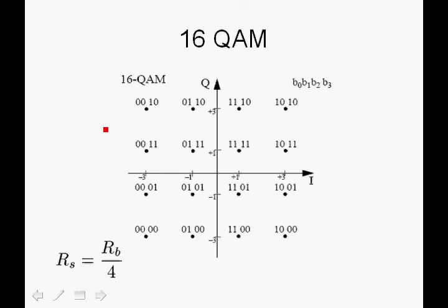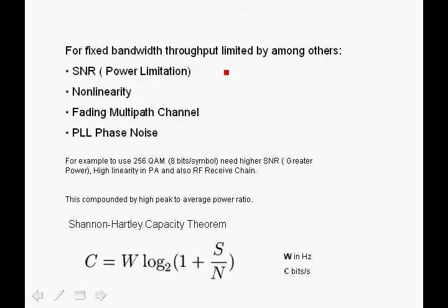Now since the symbols are then modulated and sent over the channel, we can theoretically achieve high throughput, high bit rates by using more and more points in the constellation. And this is a key method in which we can achieve high throughput or high bit rates over band limited channels: to map the bits into more and more points in the constellation. For example, in OFDM 802.11a, we use 64 point QAM in addition to 16 QAM. So if we have a fixed bandwidth, we can actually increase the throughput by mapping bits to points in a constellation and then modulating these symbols in the constellation.